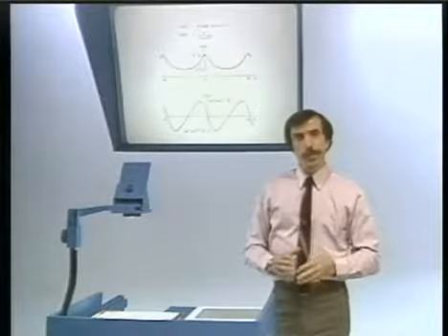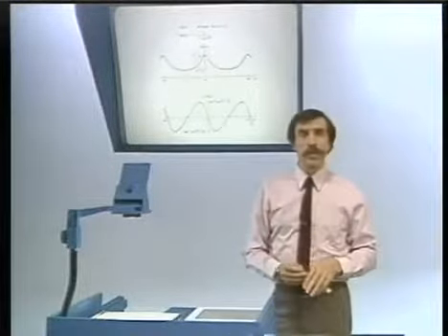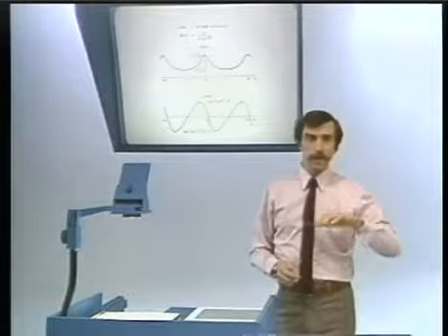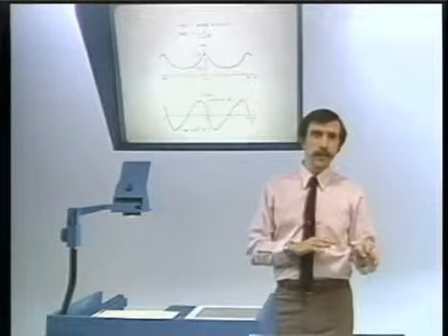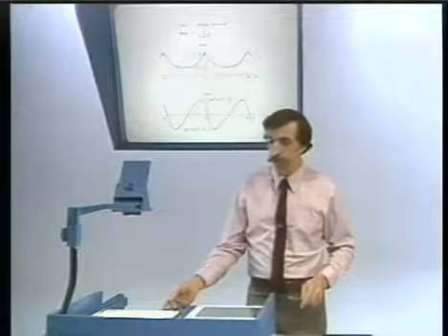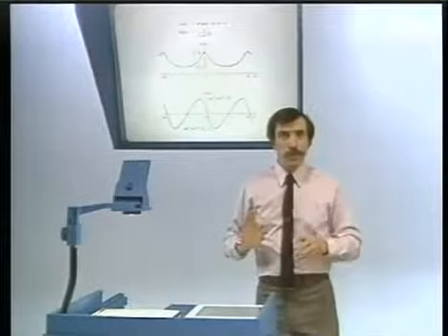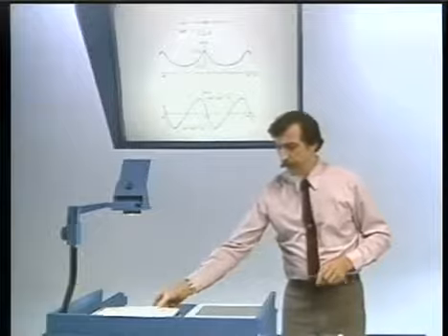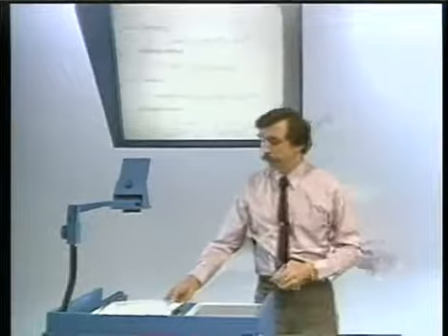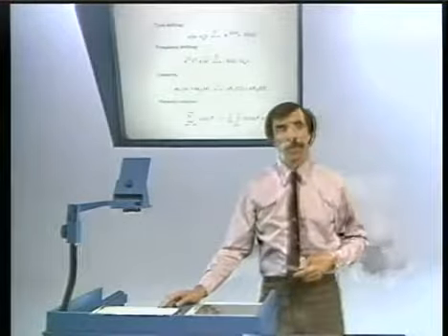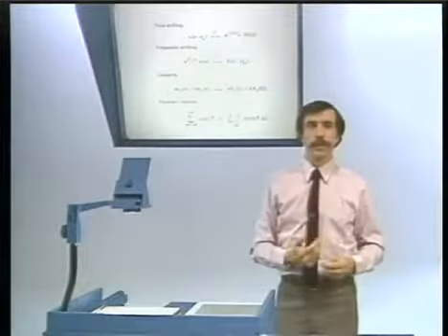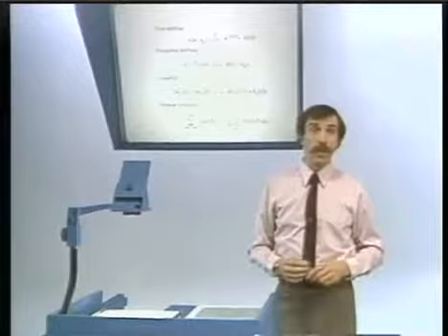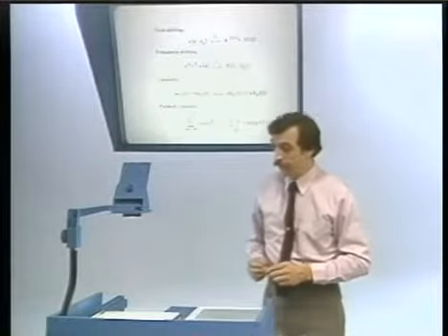Okay, so we have some symmetry properties. We have this inherent periodicity in the Fourier transform, which I'm stressing very heavily because it forms the basic difference between continuous time and discrete time. In addition to these properties of the Fourier transform, there are a number of other properties that are particularly useful in the manipulation of the Fourier transform, and in fact, in using the Fourier transform to, for example, analyze systems represented by linear constant coefficient difference equations.